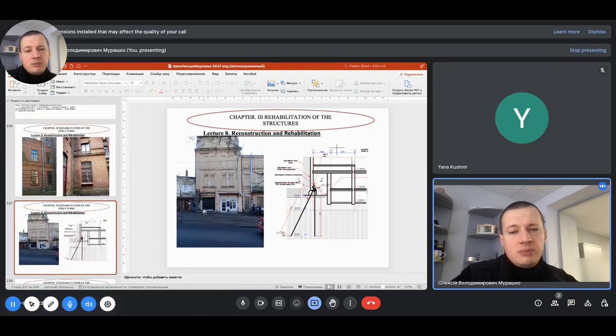This situation takes place because this part of the foundation, this wall, is located on subsiding soils, but the rest of the foundation of this building is located on the lower layer of ground, on non-subsiding soils. When water leaked from this part, it made the soil subside,